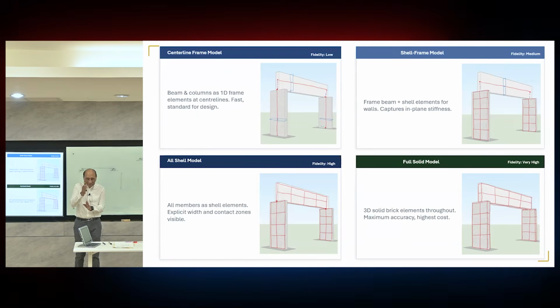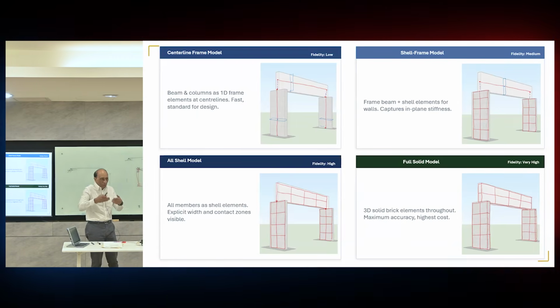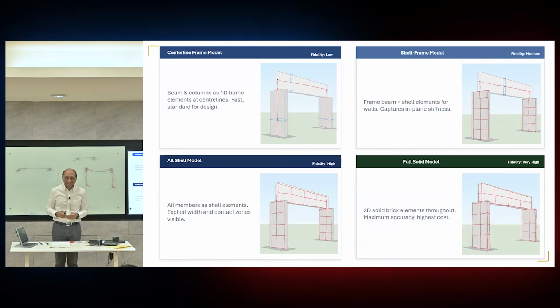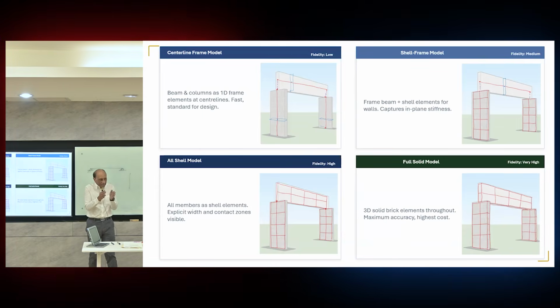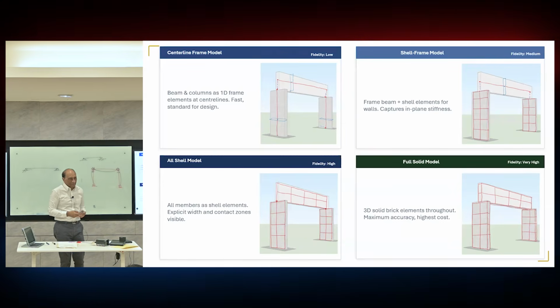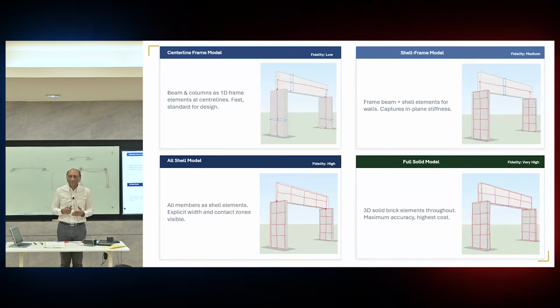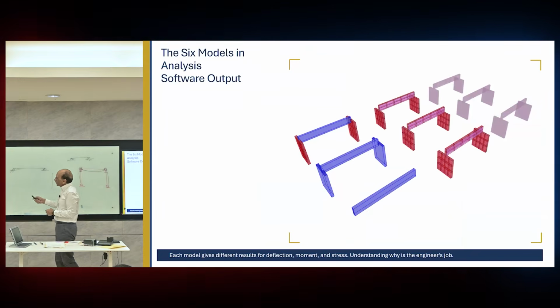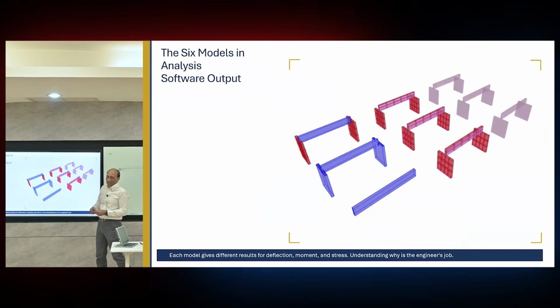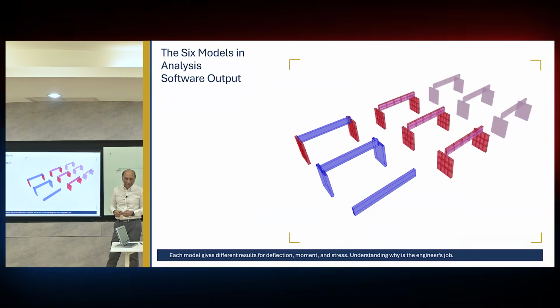You have to have matching nodes to connect. So that means more refined meshing is needed. Also, you need more lengths here to model the wall thickness, connect them together. So the meshing will become very challenging to match everything together. So I created these 6 models from that one using SAP.